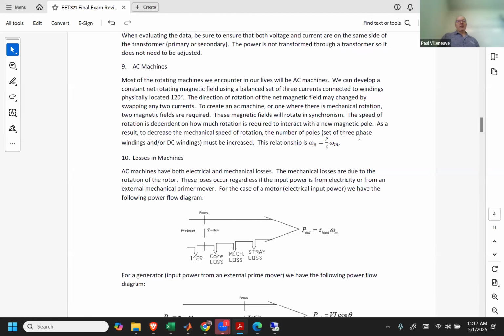It makes it easier. But we sum those together to see that we got a nice rotating magnetic field that had a constant magnitude. Its magnitude never varied, which is great because in an AC machine, we would like to produce a constant torque. We don't want a variable torque, at least from an industrial perspective. Maybe if you're driving a car and need to put more acceleration or less acceleration, we would go ahead and do it that way. But we got this beautiful magnetic field that rotated just because of current flow in the stationary set of windings.